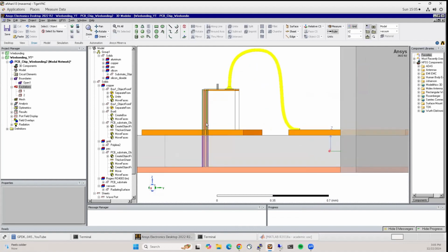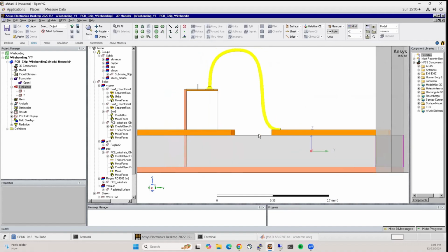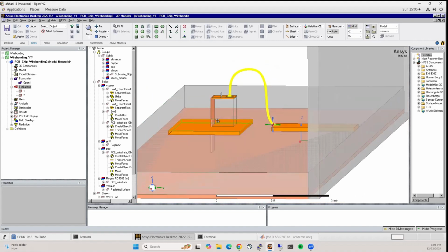It's actually not good enough. It's close because although the grounds are connected, this big piece of metal has some inductance of its own. Then there is some parasitic cap here, and you also have some inductance here. There's in fact also some capacitance between these two right now, right? So all of this matters a little bit, but we'll try to make it more accurate. So let's just run this simulation.